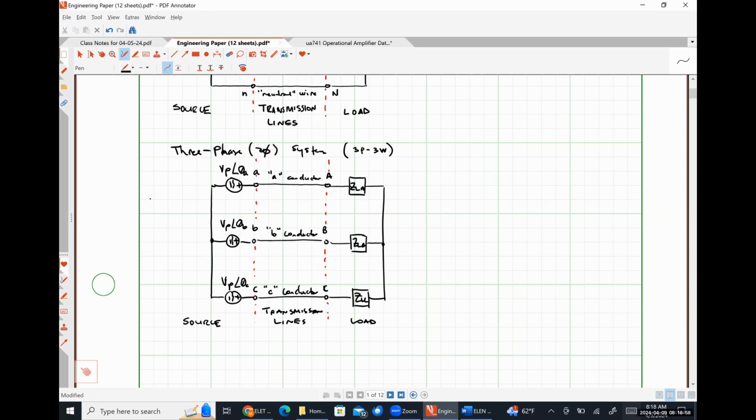So if the power surged, right? If the power was constantly changing, what do you think the motor is going to do? It's going to vibrate because the power is constantly changing. But if we can have a system where the power delivered to it is constant, it's not going to be undergoing constant changes in speed. It's not going to vibrate or anything like that. It's going to have a nice, safe, stable operating point, which is the reason why three-phase induction motors last forever.